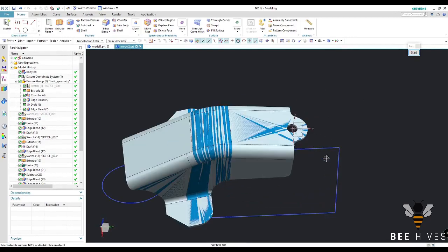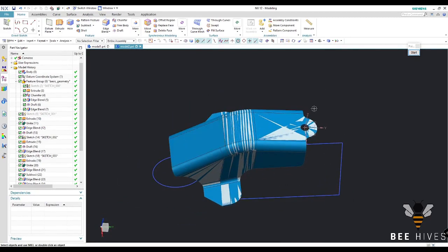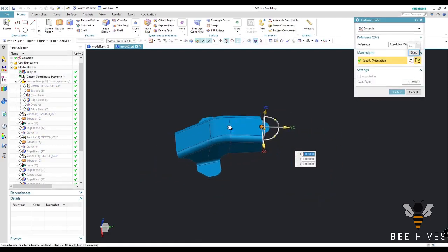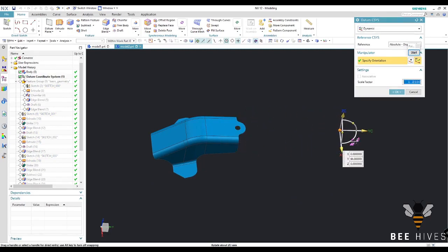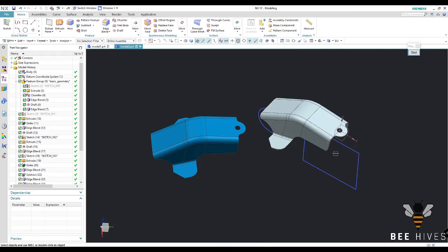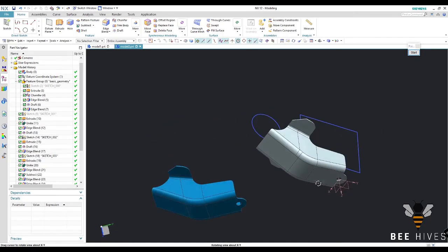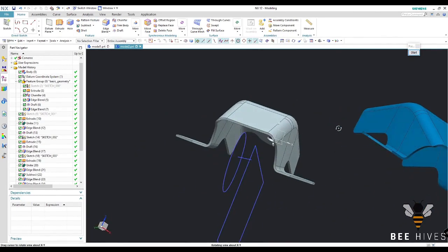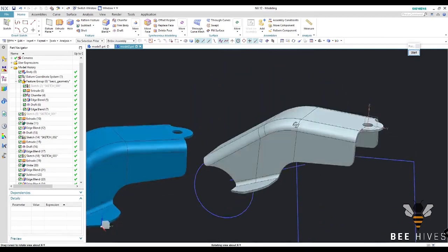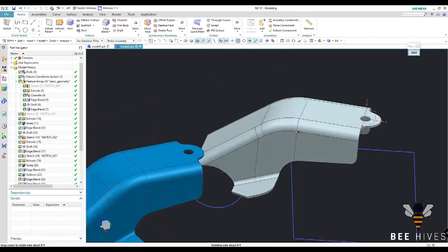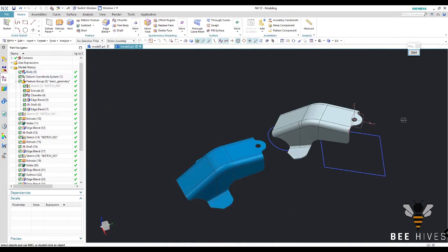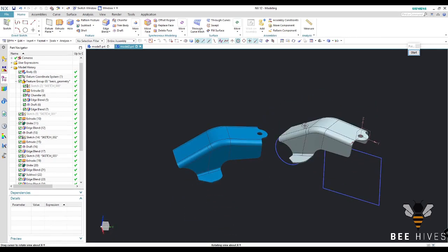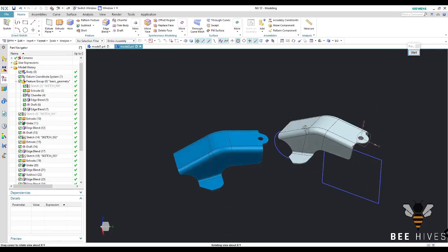Hope you like it. Always check if your model is parametric or not, just by double clicking the coordinate system. Just move it a little bit, rotate it a little bit, and say OK. Your model should stay alive. Alive means the dimensions should not change, or you should not get any error. If you are getting any error when you rotate the axis system or move the component away from the basic point, the dimension should always be maintained, and that's what a parametric model means.